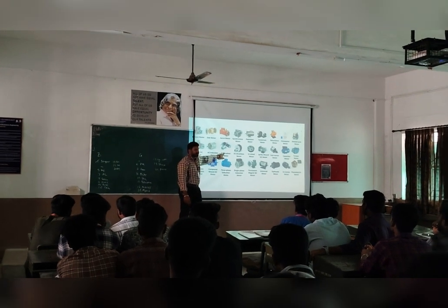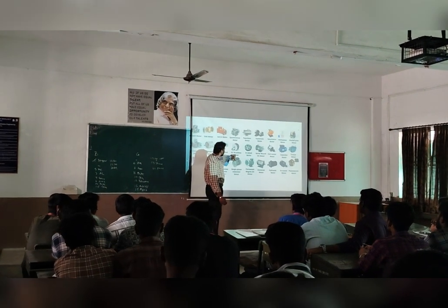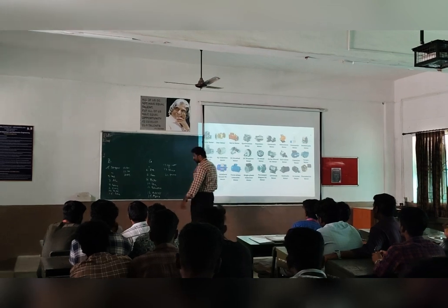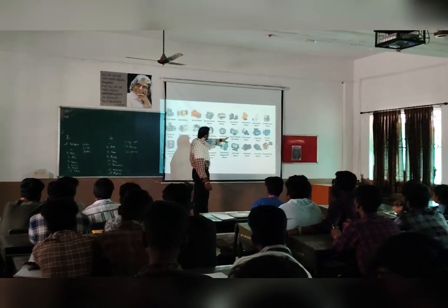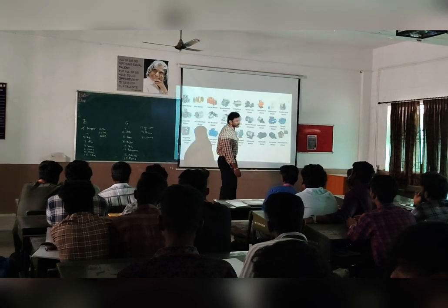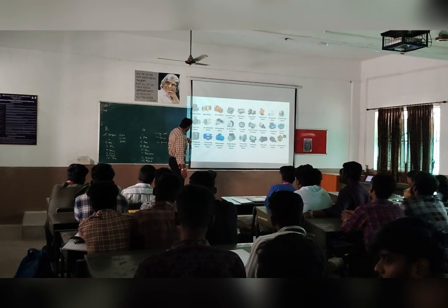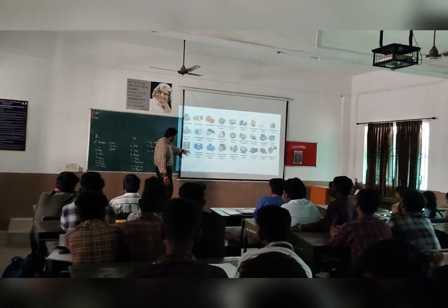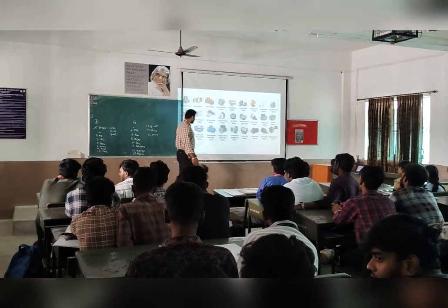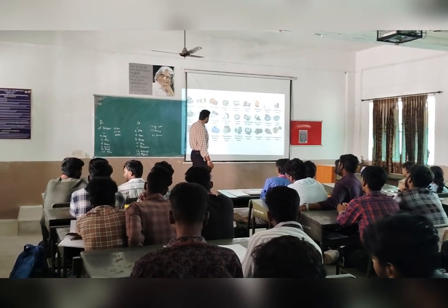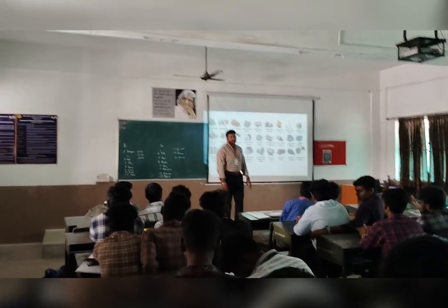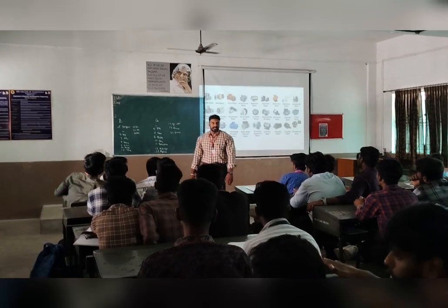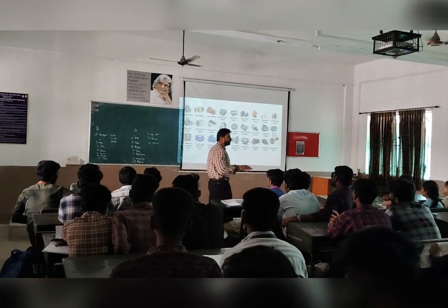And this one will be the helical gear. The helical gear changes speed and direction of movement. The teeth on helical gears are cut at an angle to the face of the gear. This gradual engagement makes helical gears operate much more smoothly and quietly than spur gears. If the angle of the gear teeth is correct, they can be mounted on perpendicular shafts, adjusting the rotation angle by 90 degrees. So just imagine that we can easily change the direction also. That will be the helical gear.